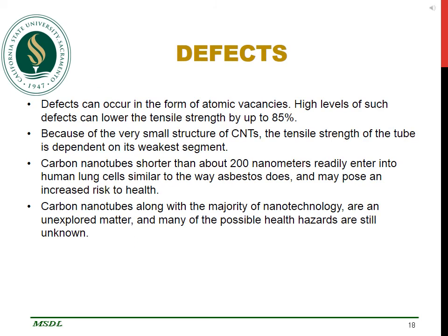There are also a number of risks and defects associated with CNTs. Defects can occur in the form of atomic vacancies. A high level of such defects can lower the tensile strength by up to 85%. Because of the very small structure of CNTs, the tensile strength of the tube is dependent on its weakest segment.